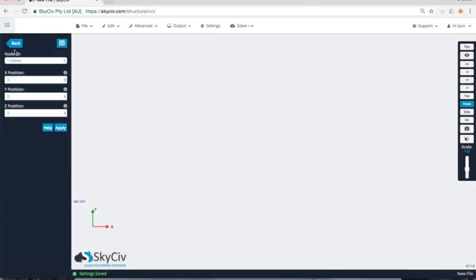As I was mentioning, we start and end all of our node positions from the start and end of each member. So I'm going to go through and just tab and enter. I can enter some of my structure properties or coordinates just by tabbing and entering really quickly. You can see I'm going to make quite a slender frame.